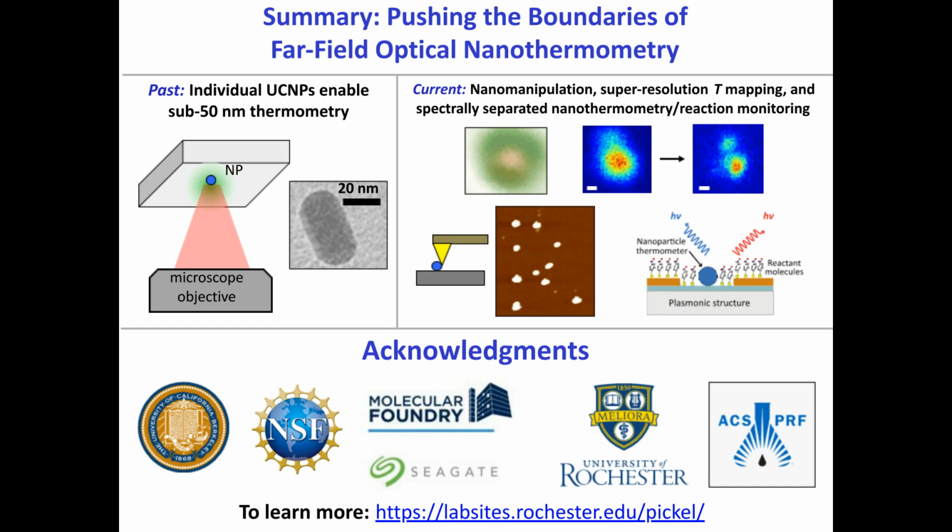Sure. Right. So as I talked about during the presentation, these excitation intensity artifacts, if you're not aware of them, can potentially really distort your temperature measurements, which is, of course, not ideal. I think there are a few ways that you can get around it. One is just to work at a fixed excitation intensity, right? If you can stay at a stable excitation intensity value throughout your measurements, then you're not going to have to worry about these kinds of effects showing up.